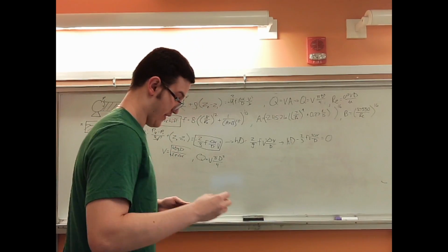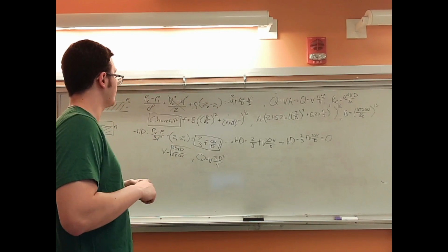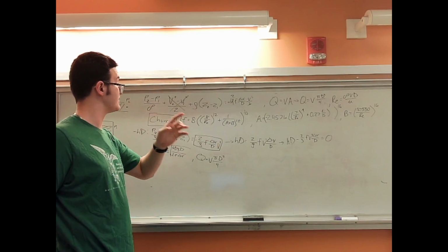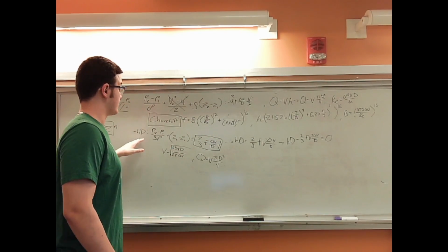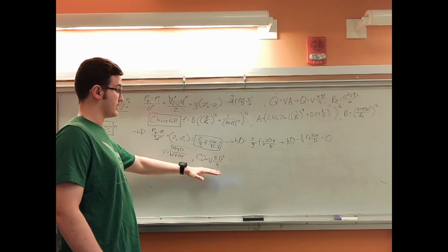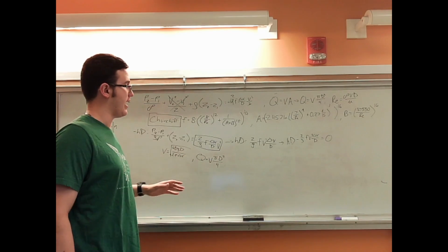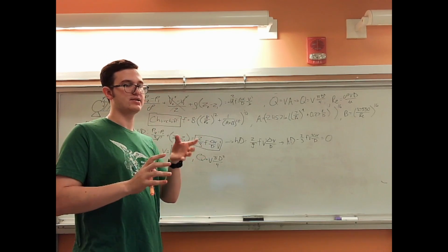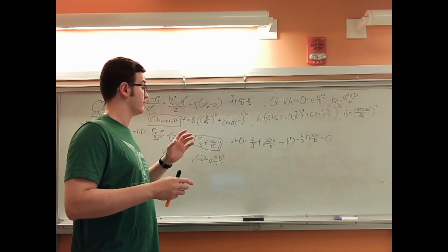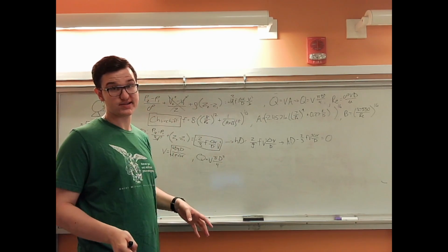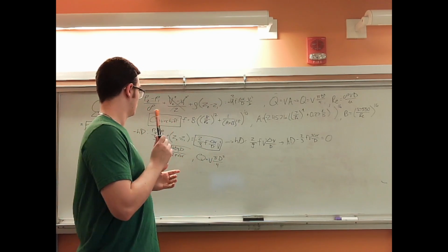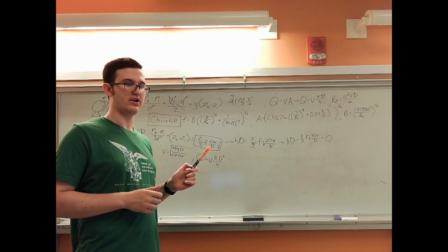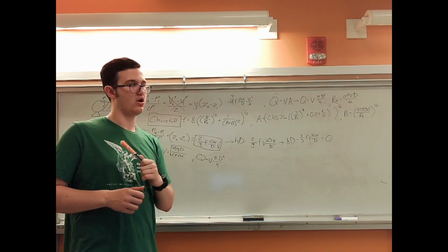So now that we have all of that, we're going to take this Churchill to find the friction factor. That's going to be the easy part. We're then going to use this head drop equation and this flow equation, and use a root solver and functions to find both of these at once. So with that, all of the derivations are finished, and we're going to transition over to the coding.